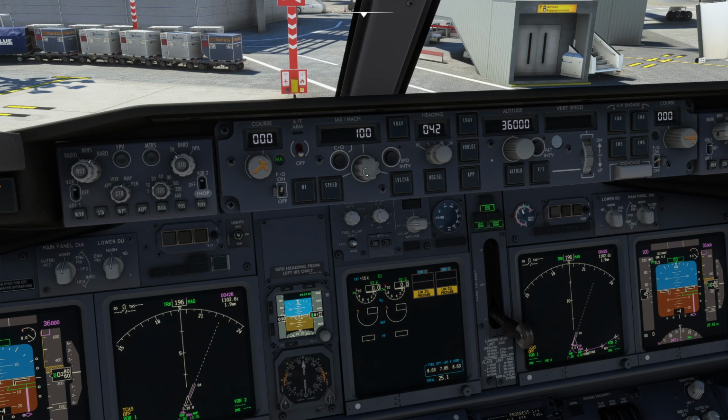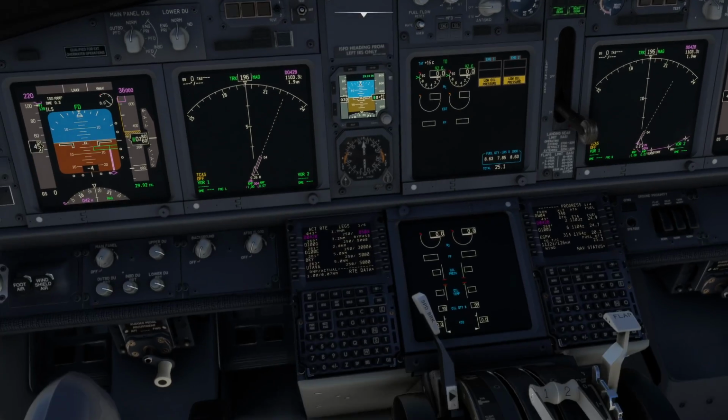We set the indicated airspeed target for the auto throttle. So we'll set it to 220 knots. We can also switch on the autopilot modes before it's engaged. As long as you've got a fully programmed flight plan and performance data and the flight directors are on, you should be able to pre-select the mode the autopilot will be in when you turn it on. So we're going to say lateral navigation mode, which means it will follow the waypoints of our plan. We're also going to say vertical navigation mode, which means it will follow any altitude restrictions.